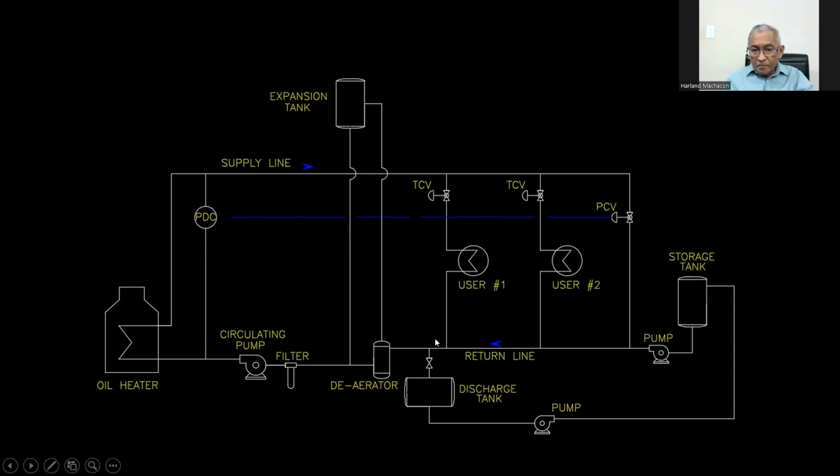Okay, and this one here is the expansion tank, so that in the event of temperature rises from the starting cold temperature, oil expands, so it will be accommodated here in the expansion tank. And if you need to add oil into your system, the storage tank has its own pump to pump it through the return line.